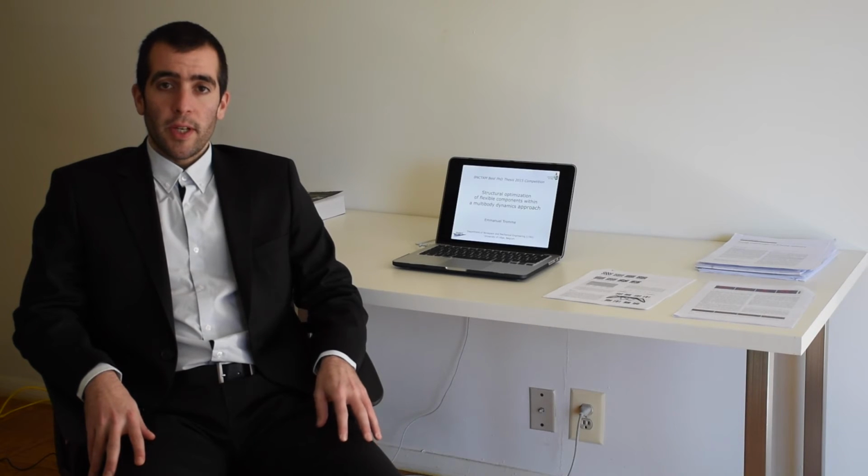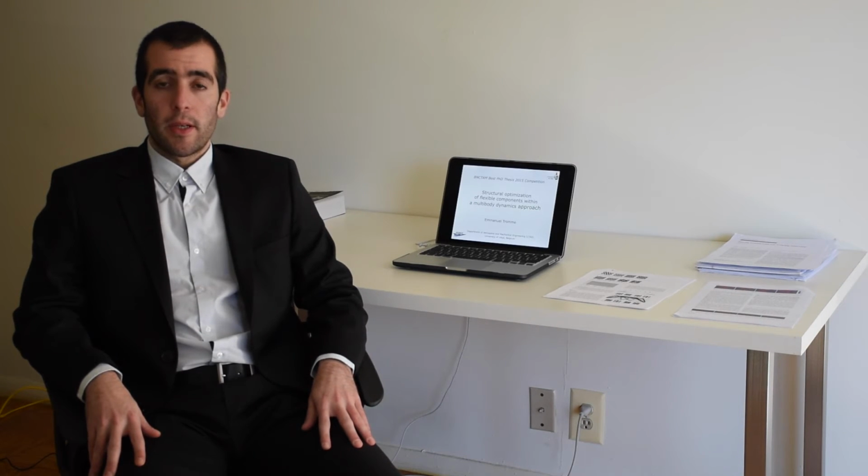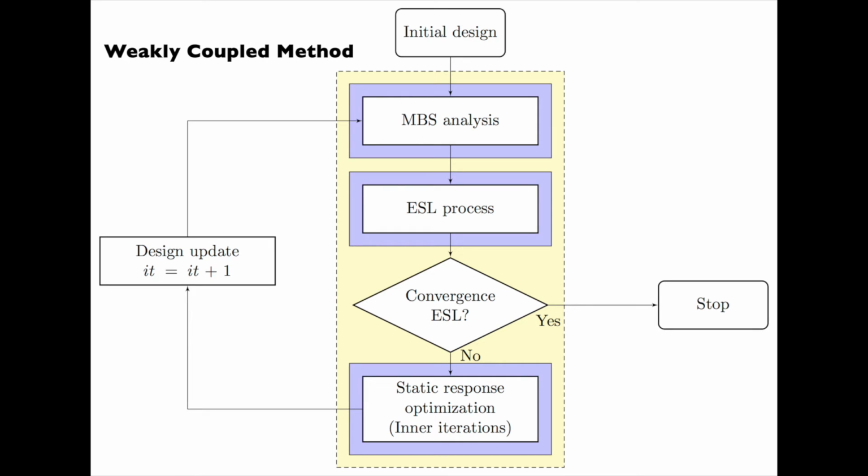In contrast to the fully coupled method, there is the weakly coupled method. This method reformulates and decouples the problem using a two-step approach. Firstly, a multibody system simulation is performed, and secondly, based on the result of the multibody system simulation, a series of equivalent static load cases are defined that are then used in the optimization process.